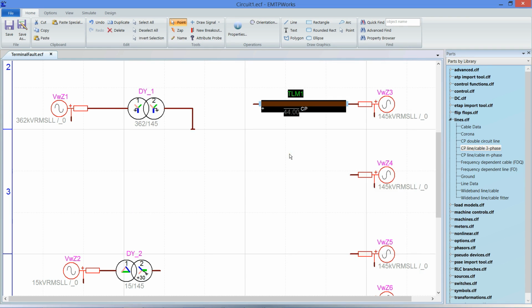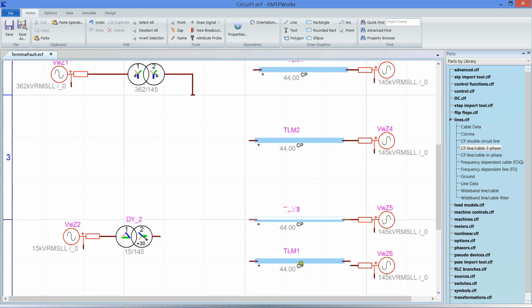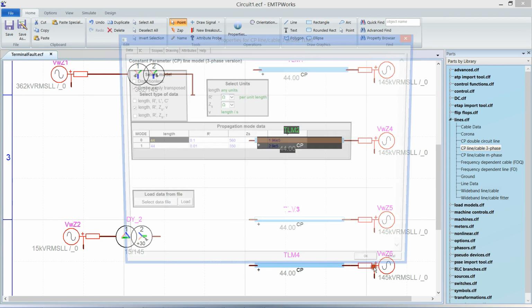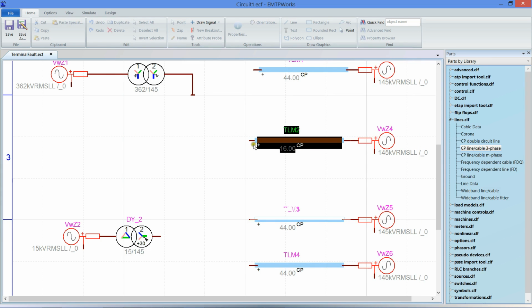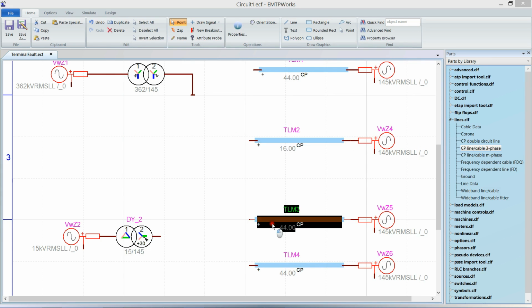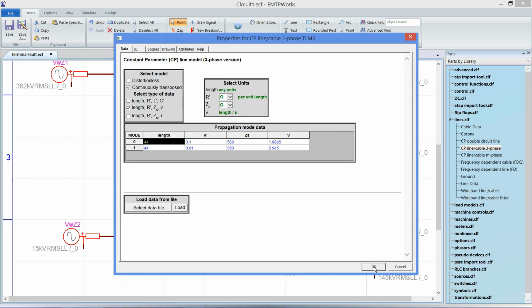After considering the length of the line, that's how you can determine the time step to use for the simulation. To have an idea, you can see the shortest line, which is this one, 16. You have to choose a time step considering the time for the waveform to travel through this line and reflect, and of course you should put several time steps to simulate that. So in the end you can find the suitable time step for the simulation.